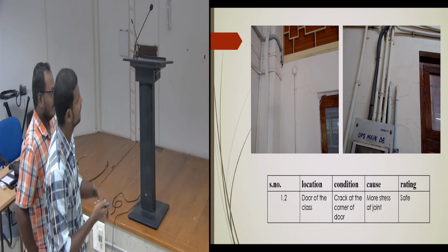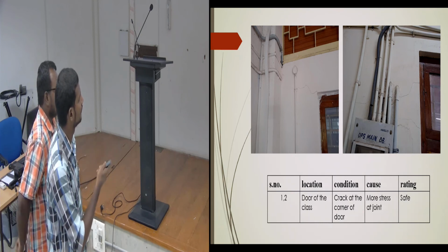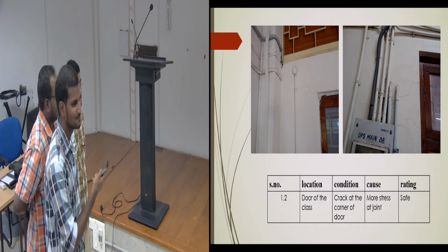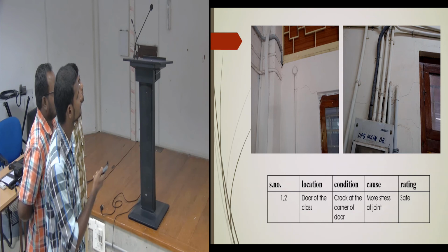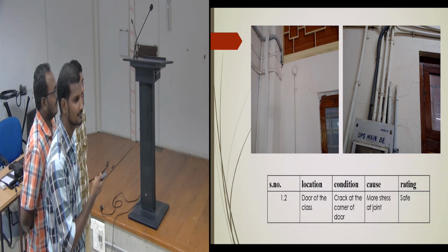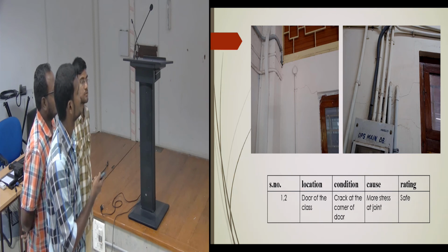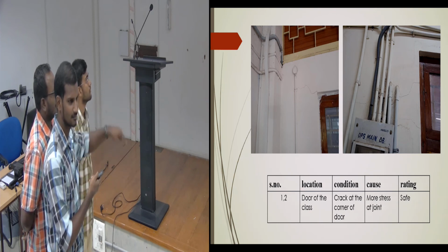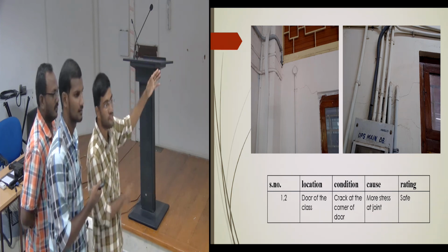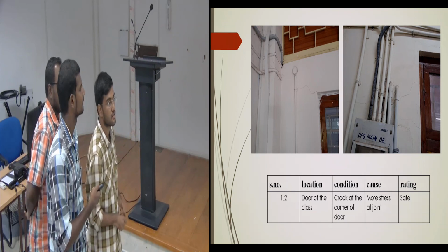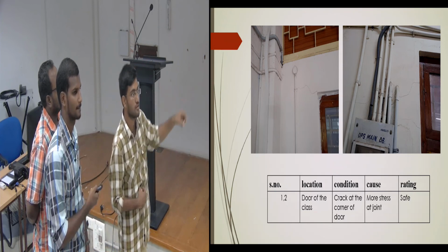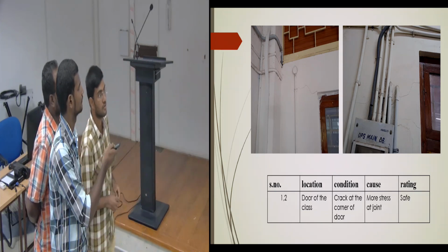What about the stress concentration? What is the connectivity between the top and this? Why only in that portion did we get a diagonal crack? Maybe due to the piping, sir. No, there is a wall, the column and the spacing between window and column is left. How about the other end? There is also a crack. That is outside. Both are outside.